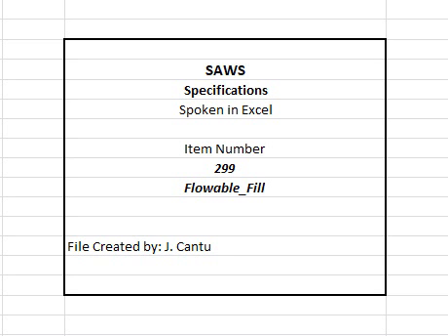Take appropriate measures to avoid excessive pressure that may damage or displace structures or cause flotation. Cease operations if flowable fill is observed leaking from the area. E. Repair or replace damaged or displaced structures at no additional cost to SAWS. F. Clean up excess flowable fill discharged from the work area and remove excess flowable fill from pipes at no additional cost to SAWS.